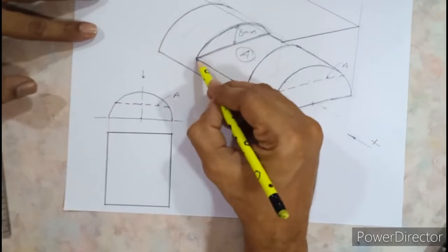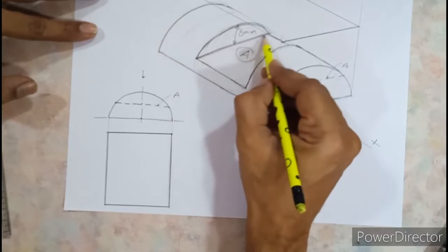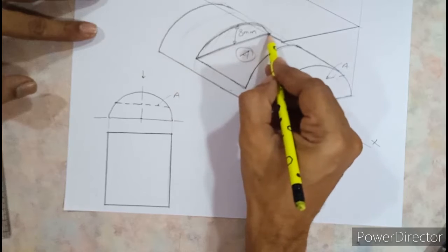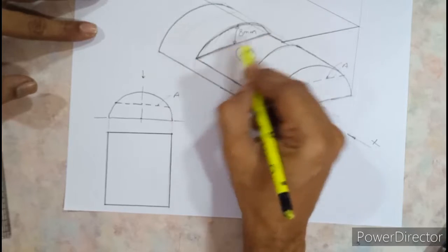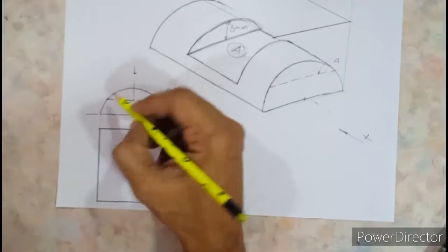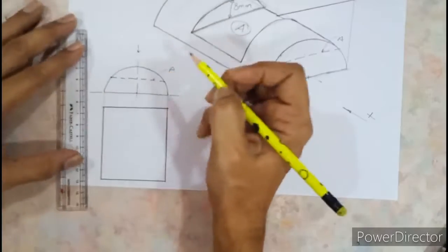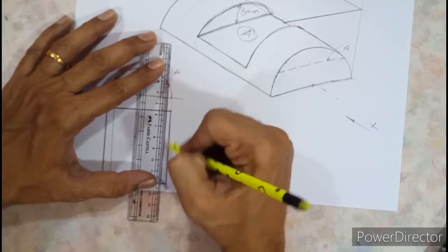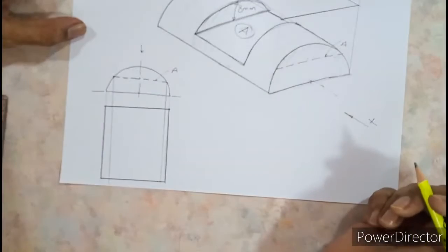If I want to determine the length, I can find it very easily by understanding that this straight line cuts the semicircle at 2 different points. If I identify those 2 points and project this down, I'll get 2 separate lines, as you can see here.